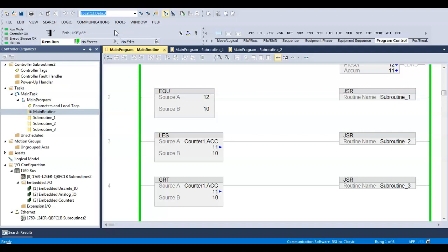Yeah. So I put, as just a little stopgap, I put switches in there. So what I would do is I would let y'all see it turn on, and before I went one more count, I would turn it off. So, a good point. So that's all I'm saying, guys. If you call a subroutine and you turn an output on, and you don't call it again and take care of that, it's going to be what? It'll stay on.